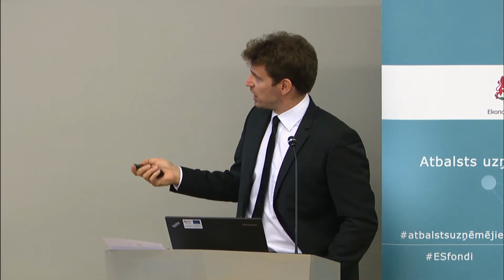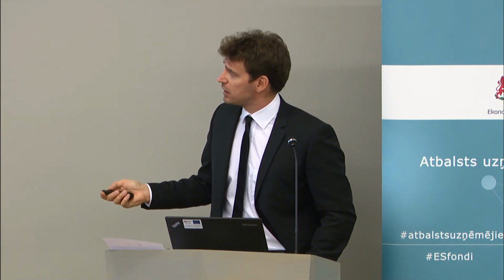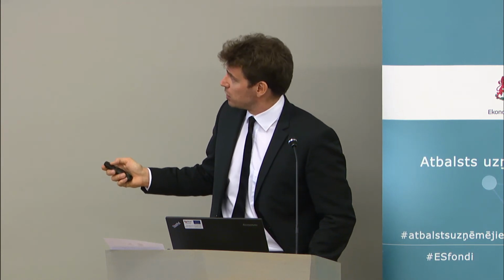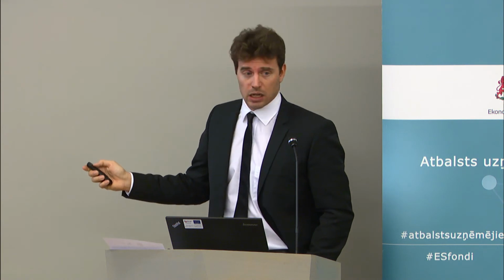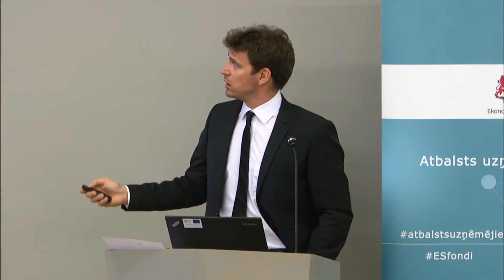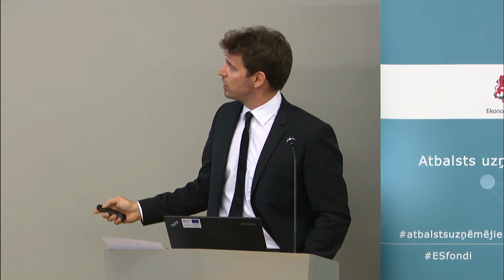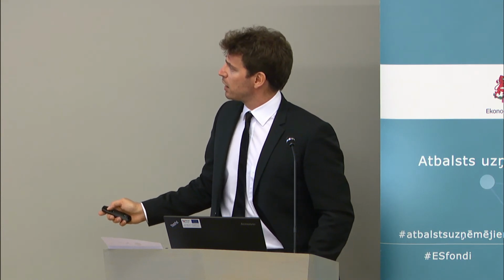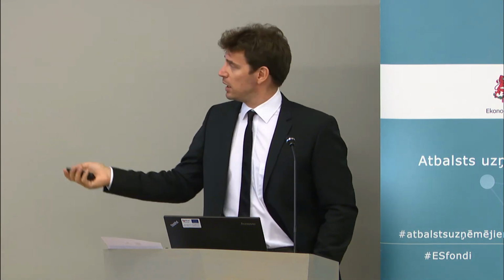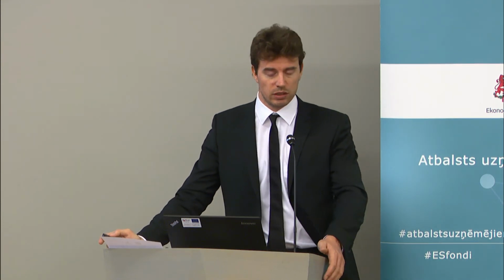But the Eurocode says that each reliability class relates to different design supervision levels. According to the Eurocode, you must make this third-party checking just if you are in the highest class: somebody else checking, a different person than those originally responsible, in accordance with the procedure of the organization. This is for second-class buildings. And self-checking, you check the calculation by yourself, but this is not much.